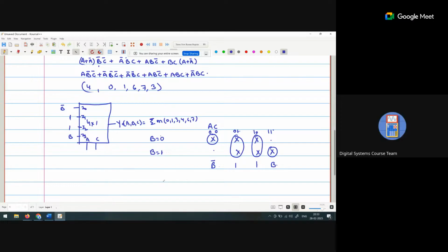It seems to me like a Karnaugh map. Okay, when A and C is 0, 0, which particular select line is selected? I0. At I0, only the term B equal to 0 is defined, so can I write it as B bar?